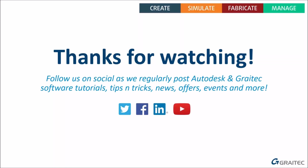So when you create a level using Project Explorer, it does have a level symbol associated with it. If that's showing in a drawing view, I presume it's a GA view, then that's part of the drawing style. So you'd have to edit the drawing style and remove the line saying display level symbols, or change that line. And editing drawing styles is a much bigger subject and something for another day. But it'll be part of the drawing style as to whether any level symbols within the scope of the camera or scope of the view are shown.